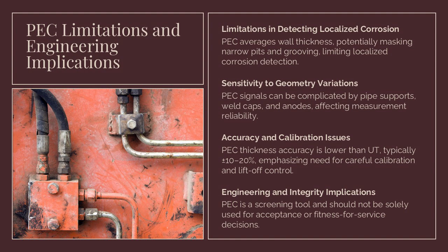From an engineering perspective, this means PEC data should not be used directly for fitness for service calculations or acceptance decisions. We should stress that PEC is a screening tool and must be complemented by higher resolution methods for defect characterization. Misapplication of PEC as a standalone acceptance tool is a common integrity management error.